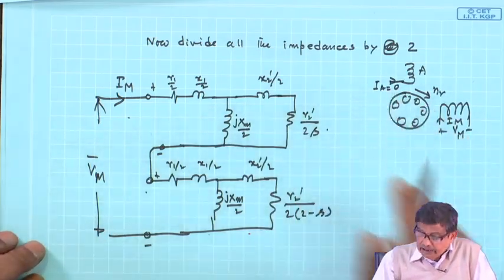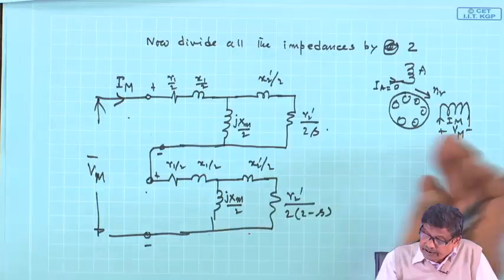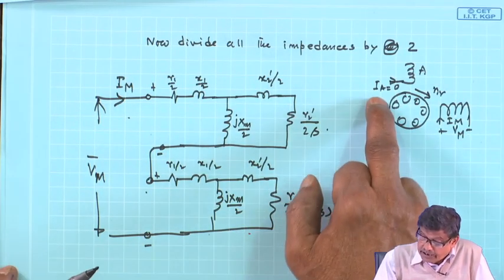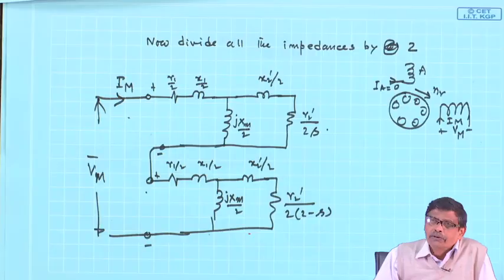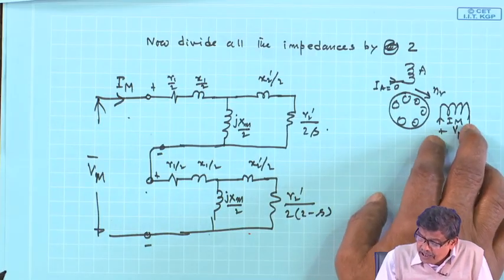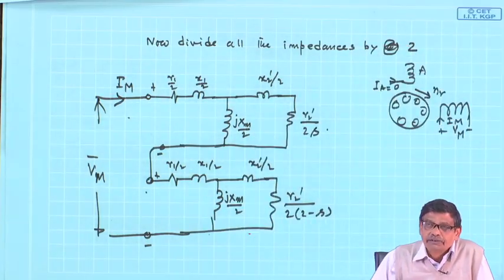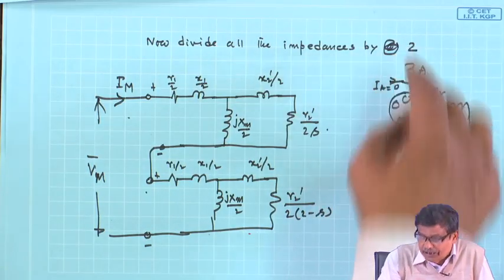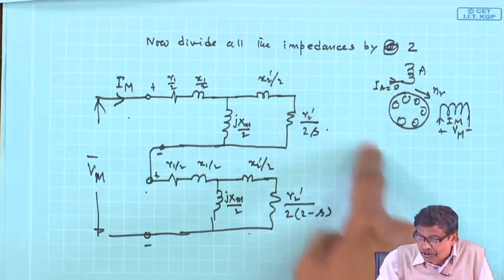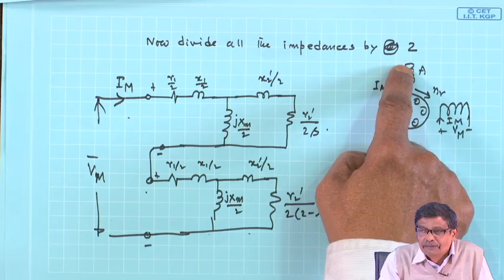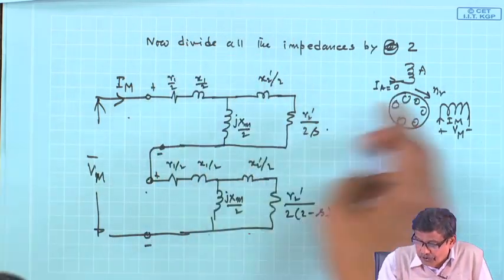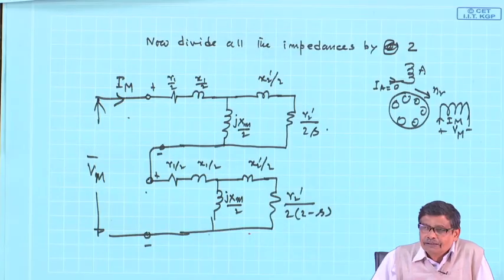Then we analyze this circuit, IA and Im, an unbalanced two phase current, because I am sure IA is 0. One may question, why not break up Vm and apply voltage 0 here? Never do that. You do not know, the voltage here may exist, because there are rotating fields. But I am certain about this fact: IA is 0 if you have not connected it.